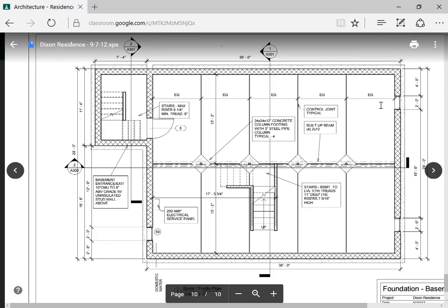And it's the same over here, instead of dimensioning to the center. And then we also show our offsets and our overall dimensions. And that's really what makes up a foundation plan, and this is going to, in most instances, be enough to show for the contractor and the building inspector.